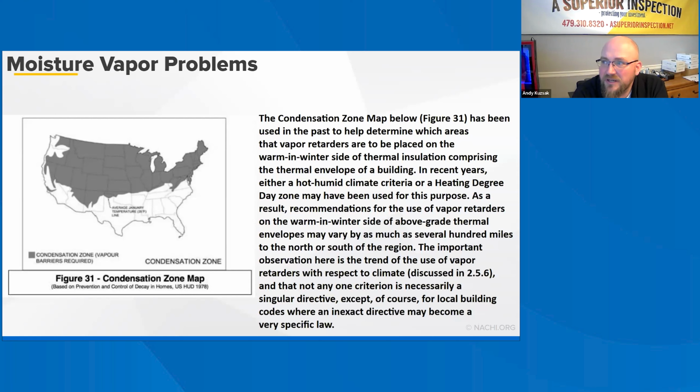High relative humidity levels might be a concern based on local experience and climate, high expected occupancy loads, unusual occupant habits, or especially tight construction. Providing for increased ventilation means selecting higher capacity fans for whole house or local ventilation devices.